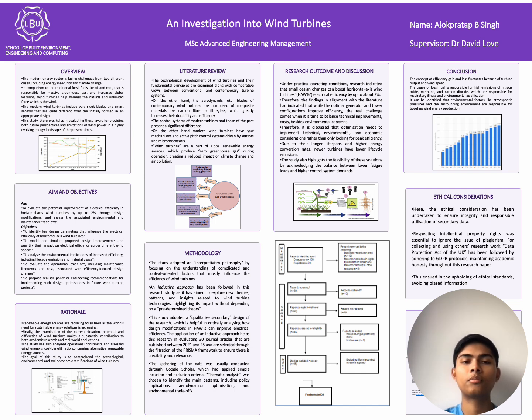While direct drive systems decrease mechanical stress and enhance dependability, they are expensive initially and you need to pay a huge amount at the start. The research recommended modular turbine architecture, innovative blade designs, and recyclable materials. And due to longer lifespans and higher energy conversion rates, newer turbines have lower life cycle emissions. The study has also highlighted the feasibility of these solutions by acknowledging the balance between lower fatigue loads and higher control system demands.